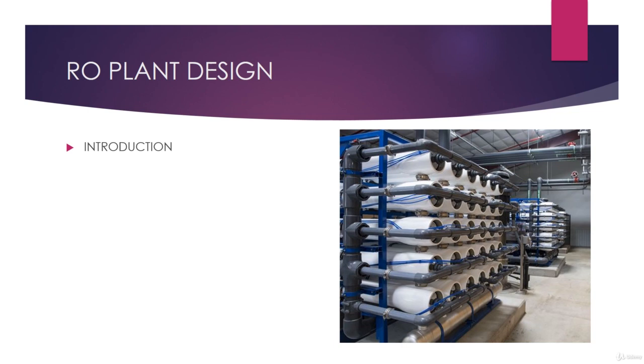In the section concerned with reverse osmosis and nanofiltration system design, we will explain the process mechanism and the principles and what the most important expressions and key terms related to reverse osmosis and nanofiltration are, such as recovery, flux, reject, permeate, and salt rejection. We will also talk about factors controlling reverse osmosis and nanofiltration design like temperature, TDS, and water source.